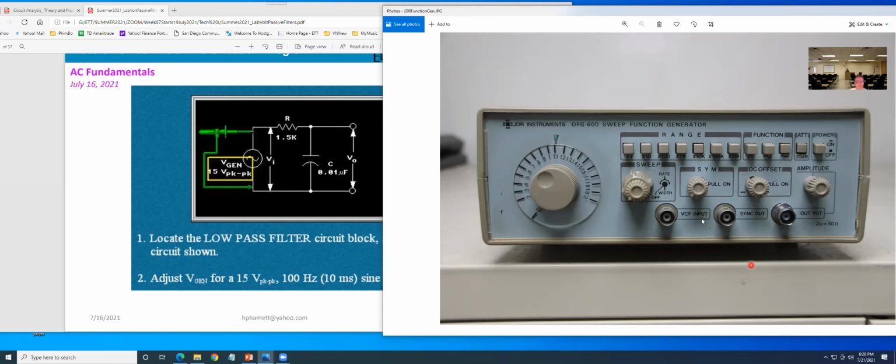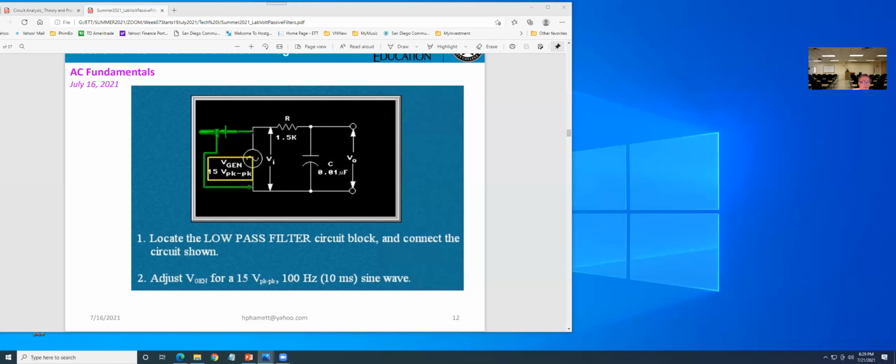You don't care what else is here. The only thing the scope is telling you is 100 hertz, 15 volt. You'll be fine. Okay. Then now you connect the generator to the circuitry here, and also the oscilloscope in this position. And suppose they display exactly the same. Okay. That means 15 volt and 100 hertz.